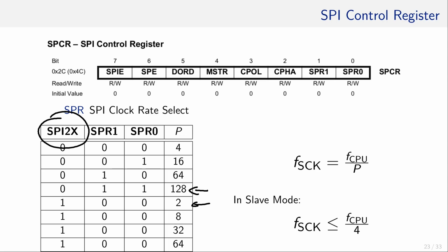Considering that one bit is transferred in one clock cycle without incurring any overhead such as addresses or parity, and since SPI is full duplex, that means that 8 megabit per second can be transferred. That is quite a large chunk of data. That are all bits for the configuration register. Let's continue with the status register in the next session.